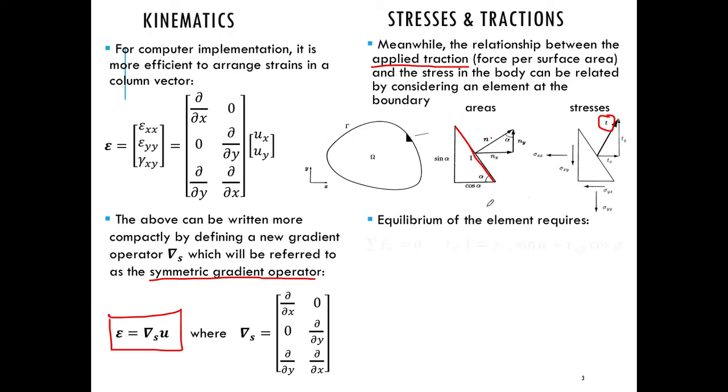So for force equilibrium, I know that my resolution of forces in the x and y direction must both lead to 0. So I've got summation Fx equals 0. Now, as I said, multiplying the stresses by the areas on which they are acting. So T in the x direction, Tx, is only acting on an area of 1.